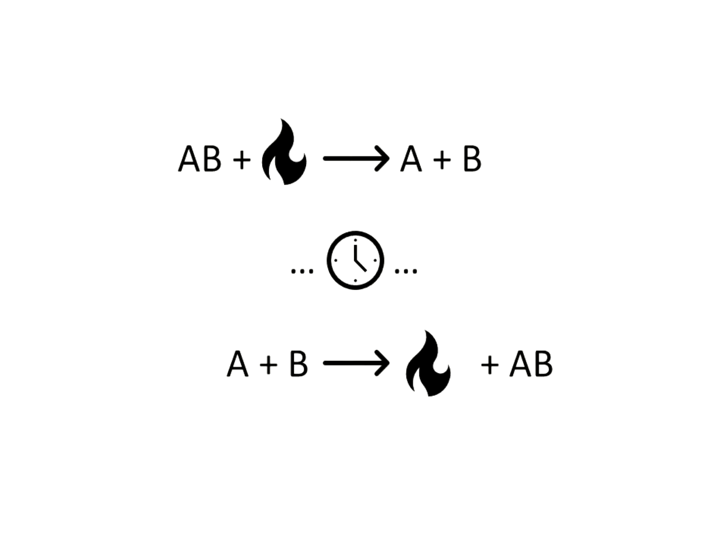The reaction that is chosen should occur at temperatures a little below the waste heat and have a high energy density. It is also advantageous if the products are easily separable, so reactions where the products are different states of matter are preferred. For example, if a solid reacts to form a solid and a gas, the gas is easily separated from the solid.